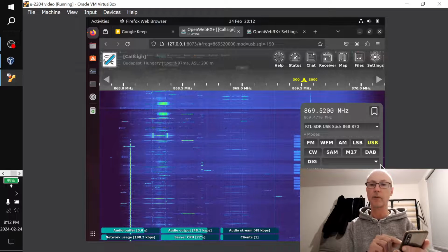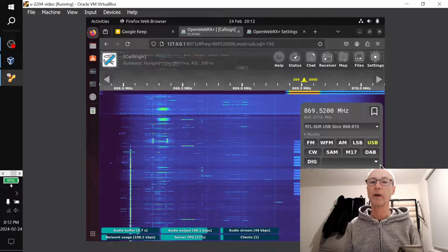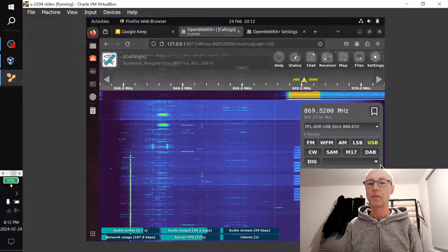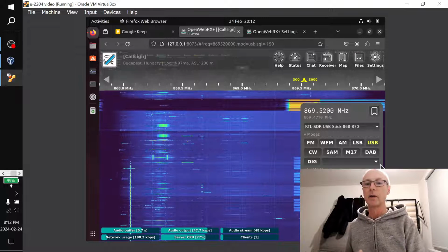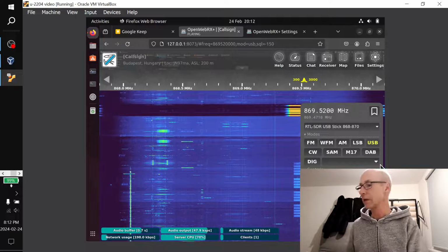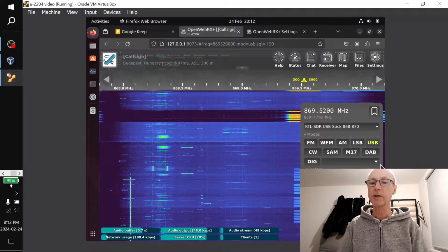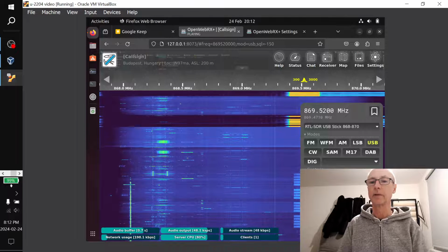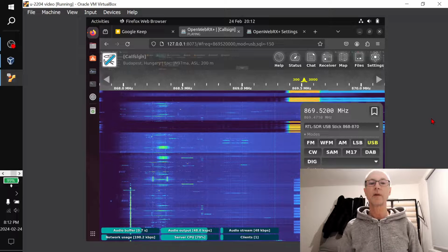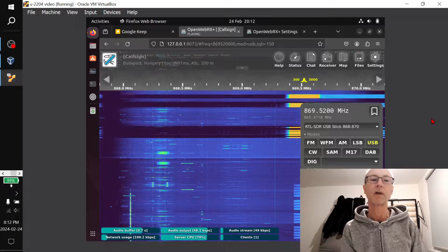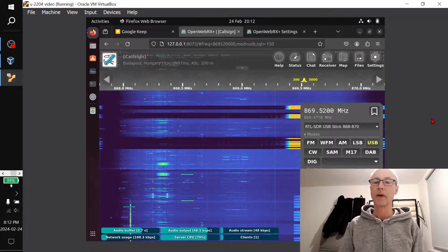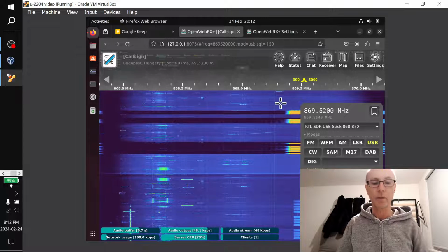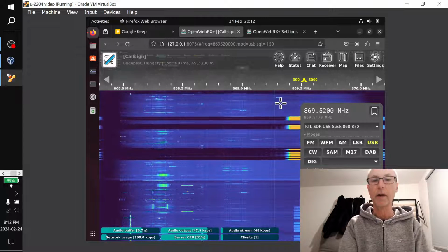So I'm going to do a trace route to another node, and oh, there you are. Those big red things are the LoRa packets being sent. So this receiver's working. Let's turn the audio off. So that receiver's working, and we're looking at it in the web browser on the Ubuntu virtual machine, which we don't have to do. So let me stop it by pressing F5.